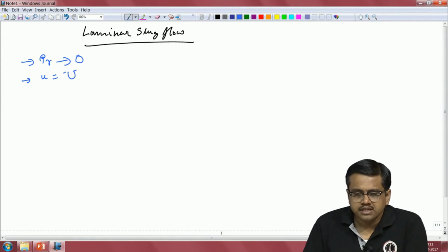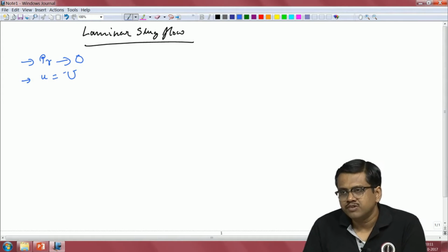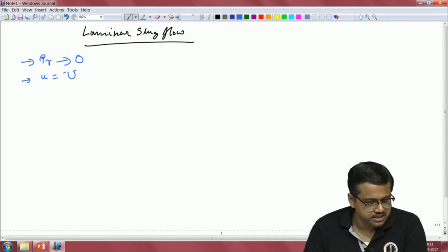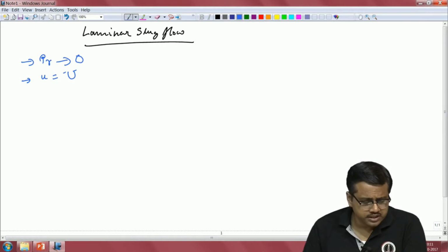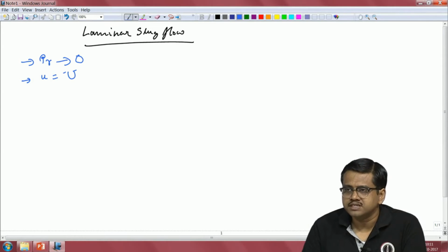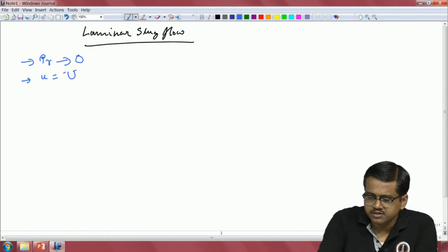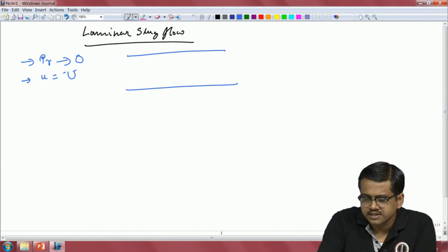Not only that, the boundary layer is always thin for the length of the pipe or the duct that we are concerned with over here. So of course the thermal boundary layer develops much faster than that. It's the velocity boundary layer which is very thin. Okay, so it's almost like a scenario like this, that this is the velocity boundary layer. There will be a boundary layer obviously.